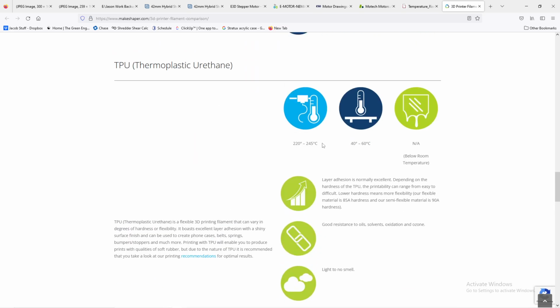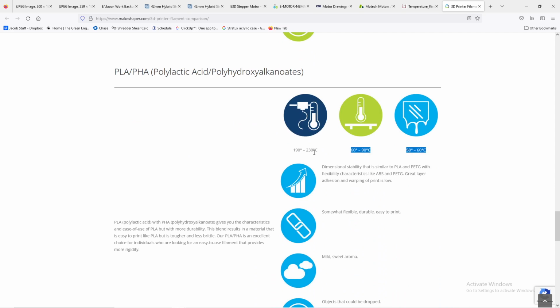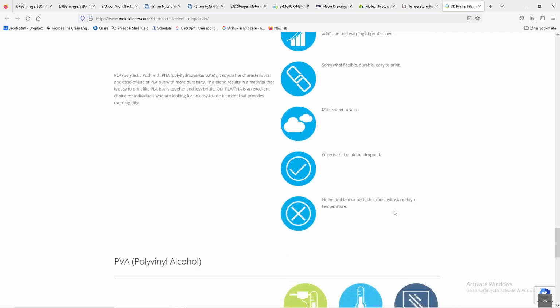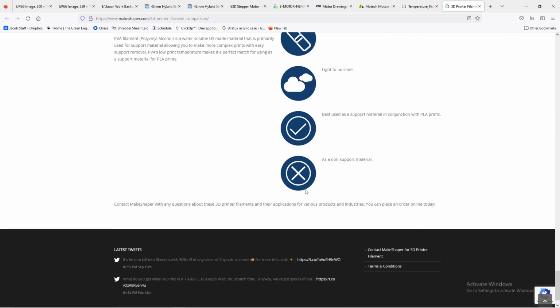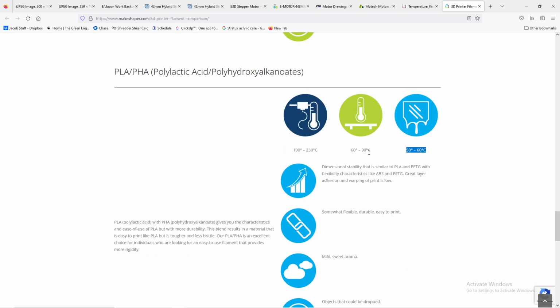And you want to get closer to this printing temperature to lower the thermal expansion, right? So here, PHA 50 to 60 C. So we have the bed at 60 C, right? And then try to heat the chamber to 60 C. But you don't want direct contact of the part to be past that 60 C.